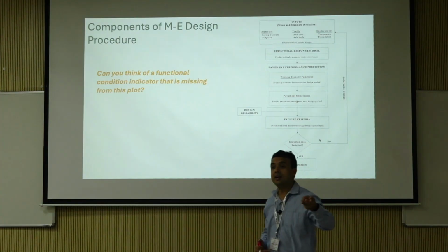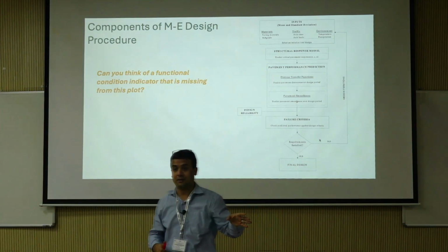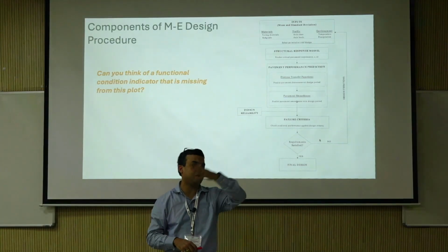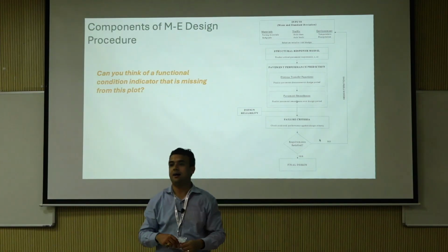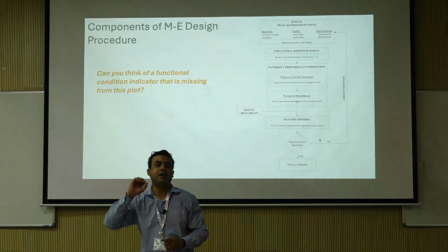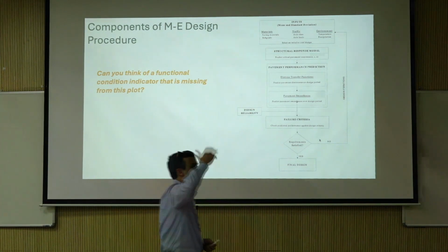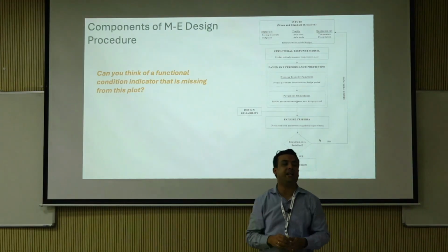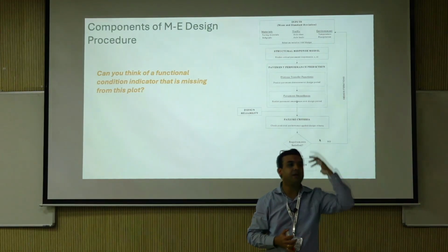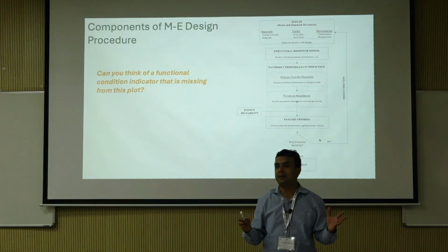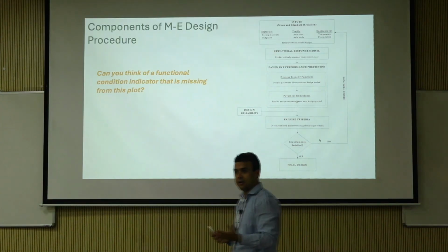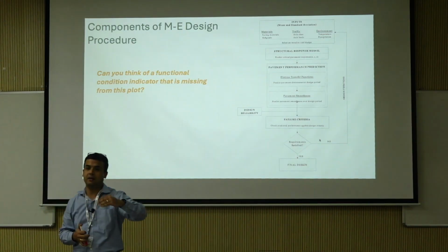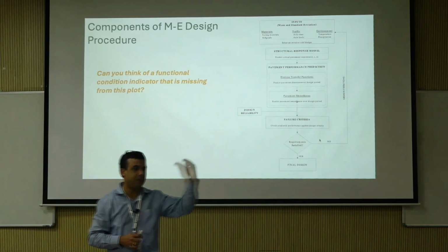Level 3 is when you don't know anything. Now you're just talking about a soil survey report and saying, okay, for the district of Khordha, this is the soil type that is there. It's a medium plasticity clay or something, or low plasticity clay. For a CL material, a representative modulus value is 15,000 psi, something like that. That's called level 3, right?